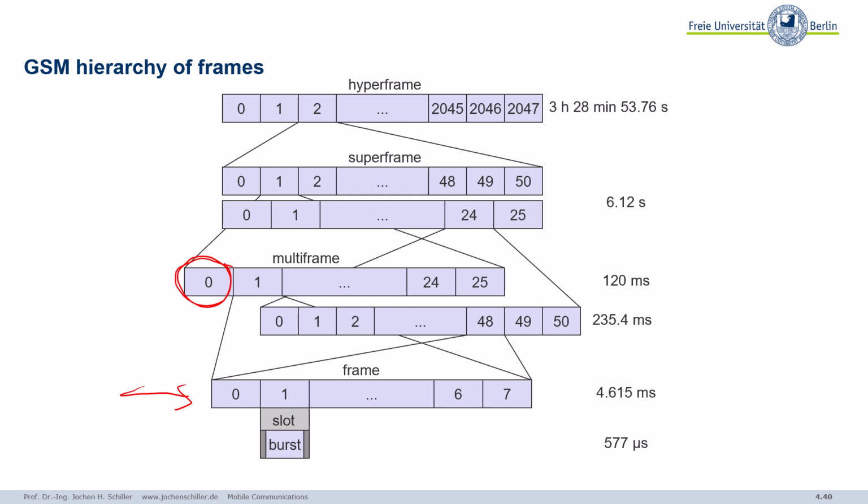So how is this then reflected in your frames? Well, actually, you're stealing user bits. That means although you have to transmit something, the system will simply steal your user bits, not transmitting user bits but transmitting control bits. You will not hear this because, for voice transmission, you have a lot of forward error correction coding. You will not really notice this. Also for data transmission, you have forward error correction, so that's not a problem. So you can actually steal, plus you assign certain slots in your TDMA frame also for control data. In each cell, you will find slots for control data.